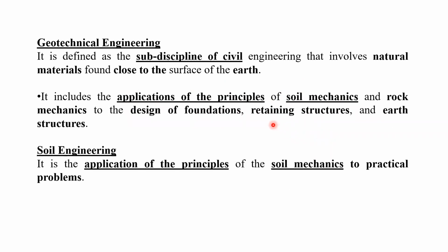What is soil engineering? Here you can see the same thing, application of principles of soil mechanics to the practical problems. See, if the bearing capacity of soil is not adequate, or if you are not going to design the foundation depending upon the bearing capacity of soil, the problem will arise below the base of the footing.